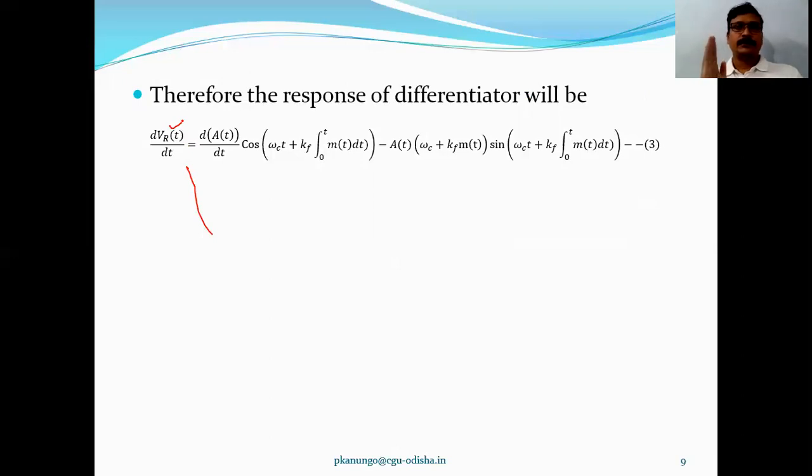Mind it, we are always working with the IF frequencies here, because we are not bothered about the RF frequency. Once it is converted by the first mixer, we get the output of the IF amplifier, which is fed to the IF filter. So the input to the IF filter is my received signal.